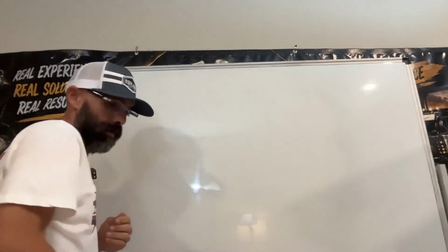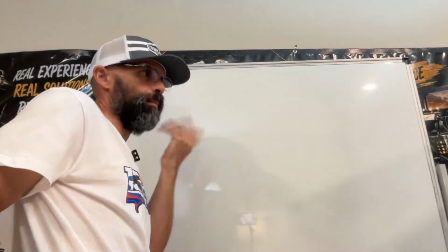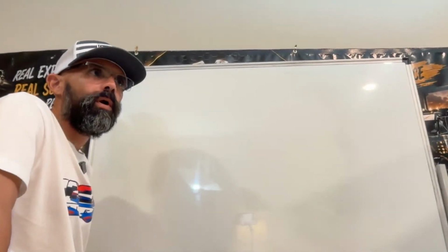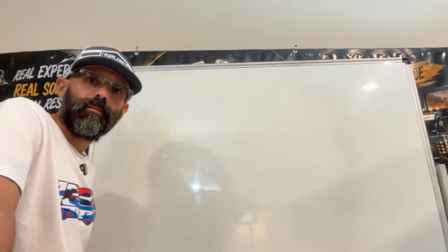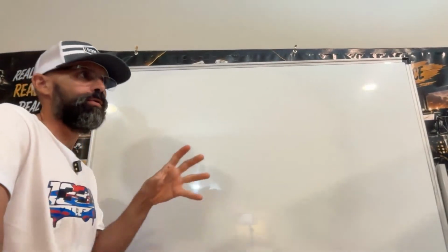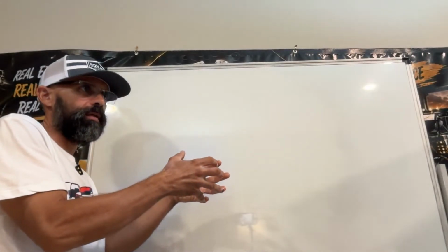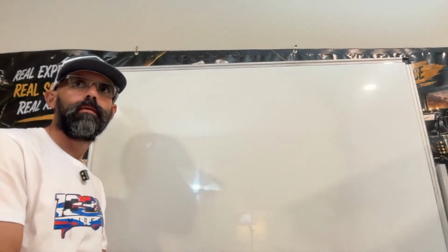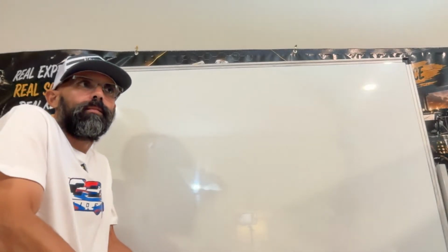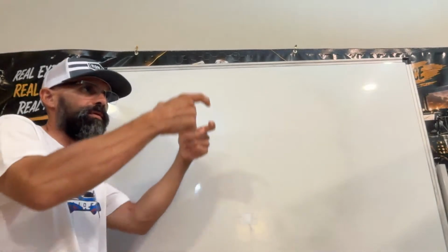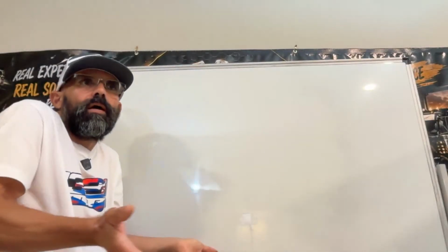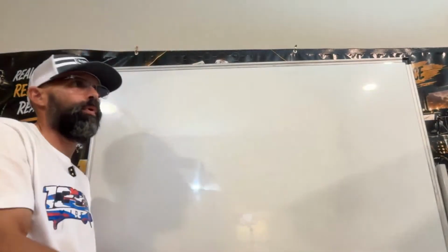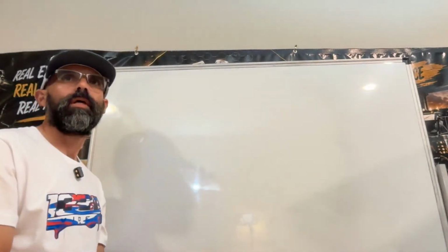I've heard people say, no, you know what? It wasn't that. I put a new pump. What do you mean a new pump? Because if you replace the whole pump, you're not gonna have that issue anymore. Oh no, this is what I did. I took the inners, the gears, and the plates, and I put new packings into a new housing. Of course, you're gonna have the same issue, because those plates that slide up and down a little bit are already worn out. Also, you gotta buy a new system, a new pump, a new tandem gear pump, and your issue is gonna be gone.